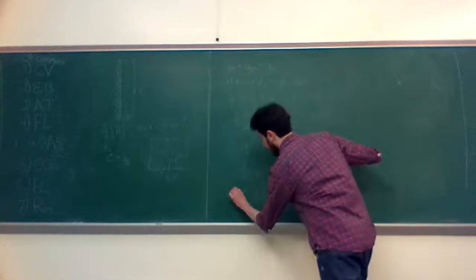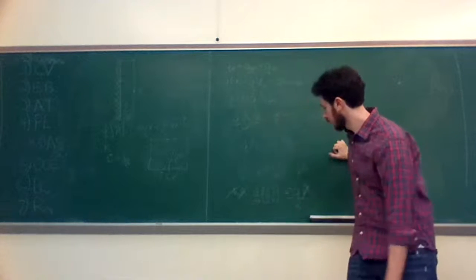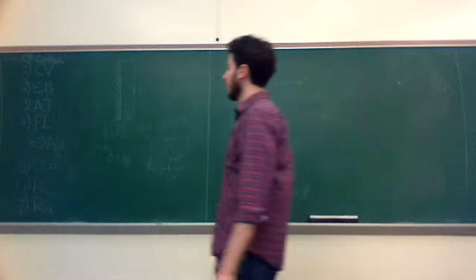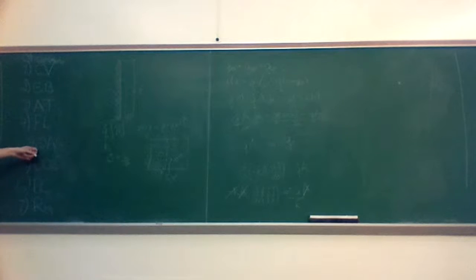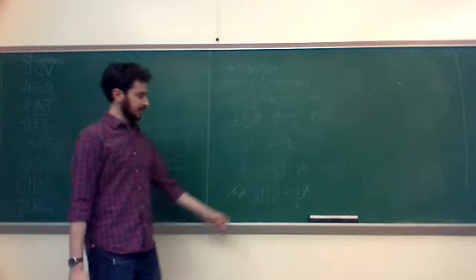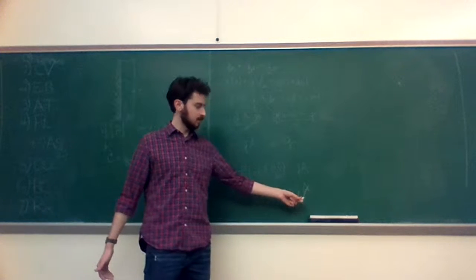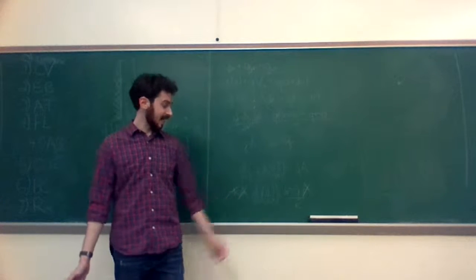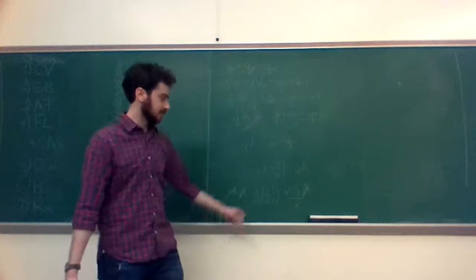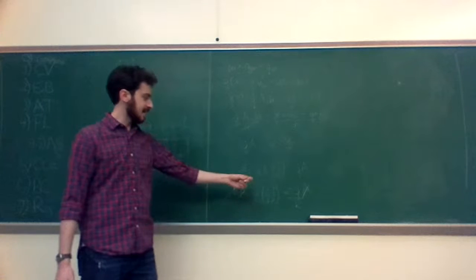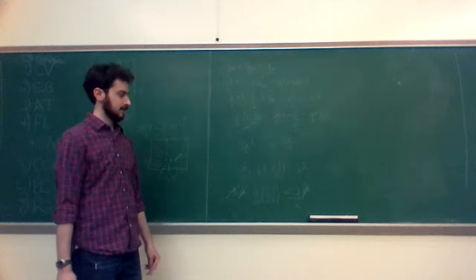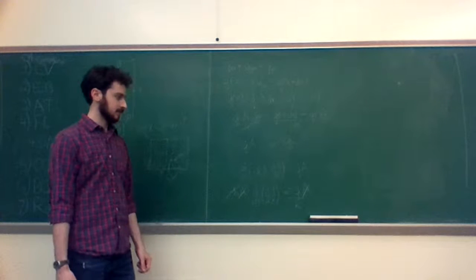Okay. Oh, so this stuff can cancel. We've applied our assumptions, and now we have an ODE. So what is the solution to this ODE? Negative 1 is always constant, q-dot we're assuming is constant, and k is constant. So this whole thing you can just call C1, right? So you've got d/dx of dT/dx is equal to a constant.